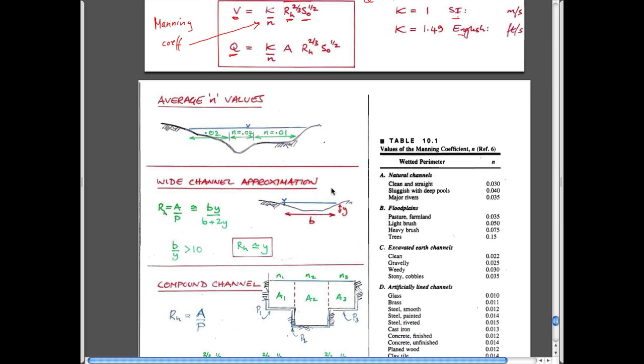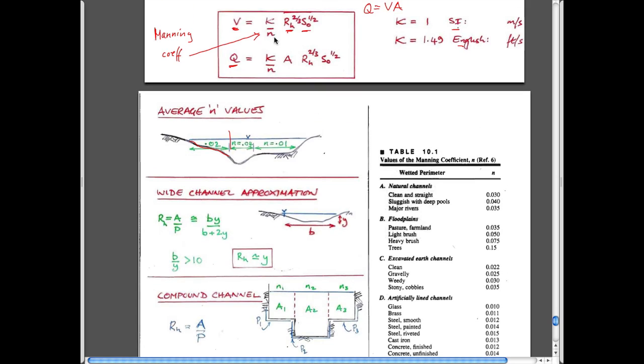And so in the same way that we talked about pipe networks where you might have flows in parallel in different pipes, you can also deal with the same if you're looking at flow in rivers, where you might have portions of a river which would have maybe a different Manning coefficient. Well, let's talk about Manning coefficients. These scale with this parameter which describes the resistance to flow. So I suppose, all things being equal, the velocity will be highest when you have a small Manning coefficient. A small Manning coefficient means presumably you have glass-walled boundaries to your open channel.